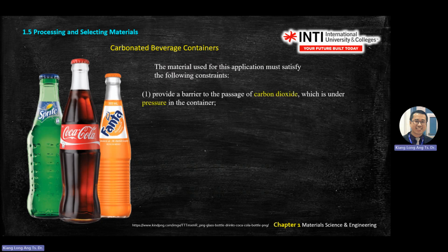First, you know that in all these carbonated beverages, inside there you are using CO2, right? And inside there they have a pressure. So you need to consider what CO2 can do to the materials, what pressure can do to the material when you do design. Then the container that you use for the beverage cannot be toxic, it cannot be reactive.